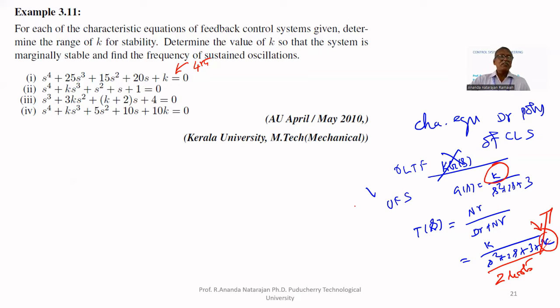Your bike you are riding, the order is third order onwards. If you increase gain, the poles on the left hand side will move very close to the j omega axis. So if any disturbance comes, you will oscillate. You can notice when the speed is very high, you cannot take decision. It will oscillate because the poles are very close to the j omega axis. That's why speed is dangerous.